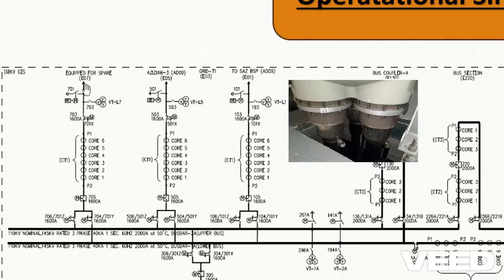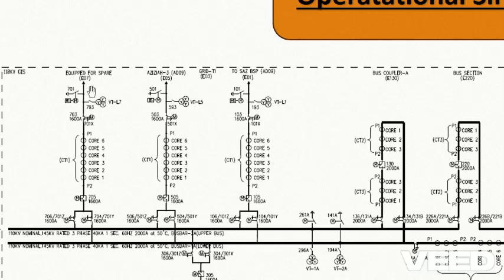Here in some substations there are some surge arresters on the GIS, but in this station specifically there is no surge arrester. The first point of entry of power is at the surge arrester. A surge arrester is used to arrest any surges from the network to protect this equipment.